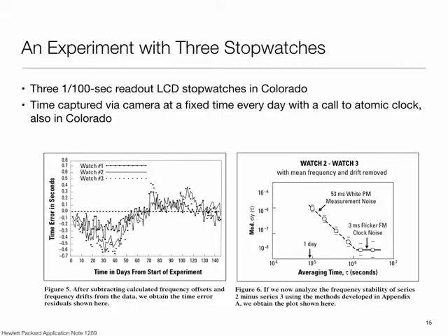So the upshot is that the villain in the story really is the drift in the clock, because all other sources, any constant offset, whether in frequency or time, you can begin to learn through some sort of message exchange. We'll see in the next slide set how one can do it, but both time offset and frequency offset you can learn, and by making multiple measurements, you can learn it to high accuracy. Again, the problem comes because clocks change, and they change in an unpredictable manner depending on the environment.